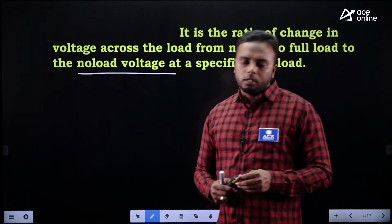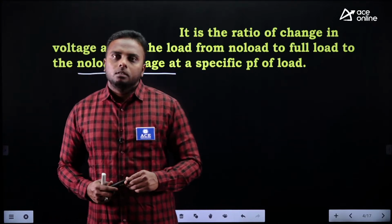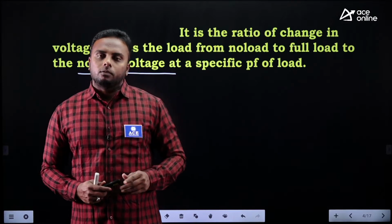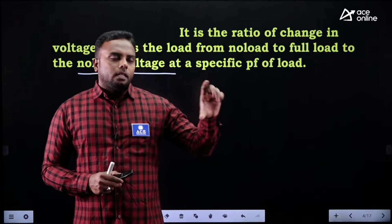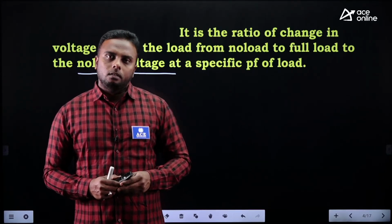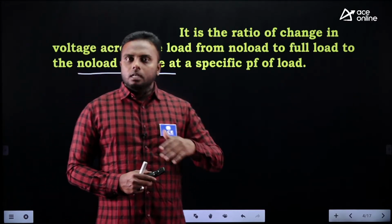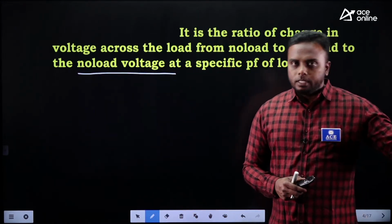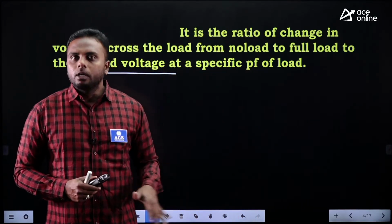Just like in power systems, transmission lines also. When capacitive loads are connected to a transformer, the terminal voltage across the loads will be more than the EMF of the transformer. Suppose 200 is the transformer secondary EMF. At the terminal for a capacitive load, terminal voltage will be more than 200, let us take 205 volts. Then the direction of current will reverse, no? Receiving end voltage is more than sending end voltage. If receiving end voltage is high, loads may get damaged. So there we do tap down.